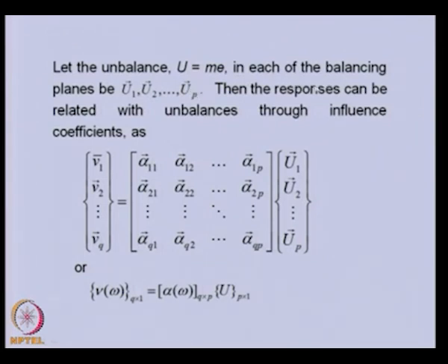Now, we are relating the response, that means the vibration of the rotor, with these unbalances through influence coefficient, as we described earlier, that we can relate the displacement and the force with the influence coefficient. This kind of thing we already discussed for the case of rigid rotor, in which these are the locations, the measuring plane location response, that is q in number.